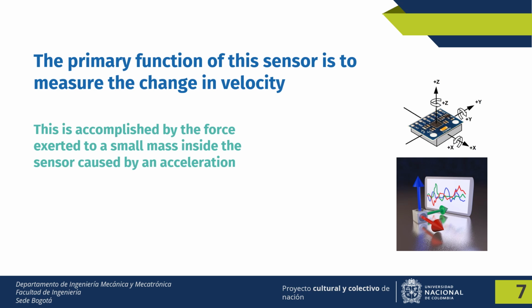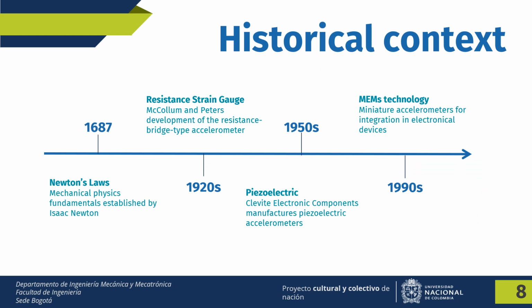Single and multi-axis accelerometers can detect both the magnitude and the direction of the proper acceleration as a vector quantity, and can be used to sense orientation because the direction of weight changes, coordinate acceleration, vibration, shock, and falling in a resistive medium.